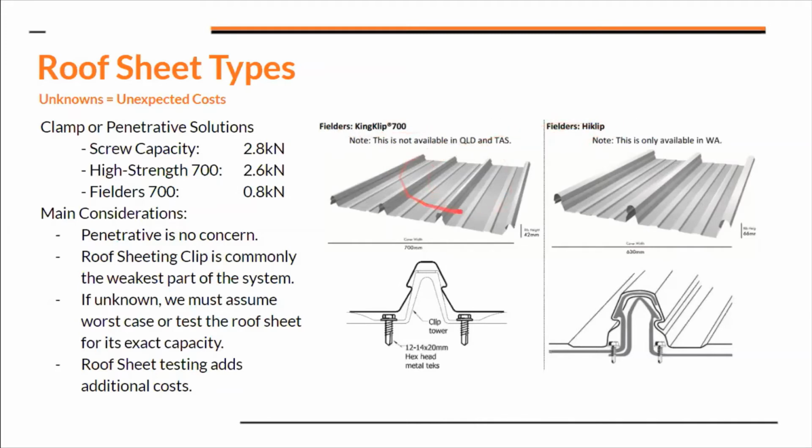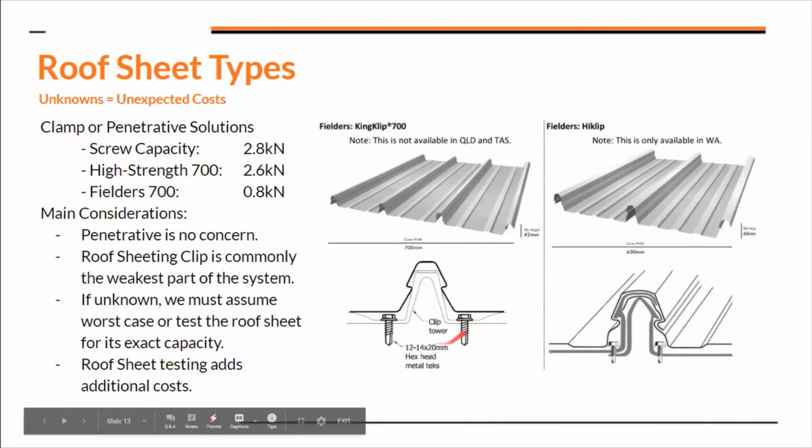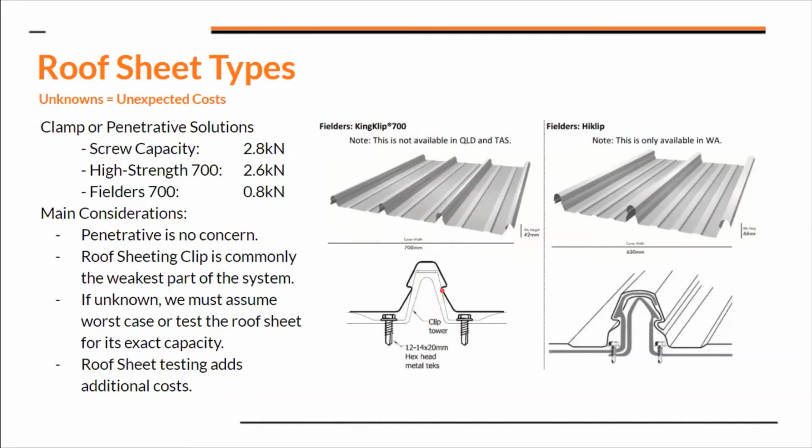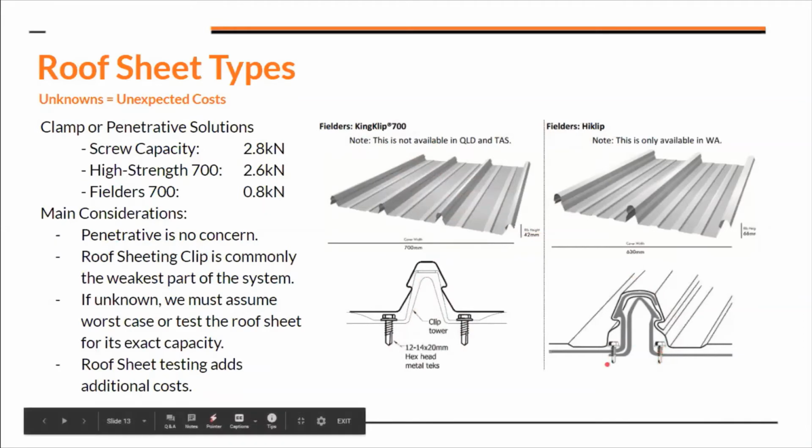Now, how these roof sheets are actually installed on site is that they have these internal clips. A roof plumber would come through and install these internal clips into the structure, whether it be timber or steel. They would screw these internal clips down, and then they get this roof sheet and pop it on top and press it down, and it kind of locks into this clip space. In the same way here, they've screwed these little things down, and then they've put this roof sheet on, interlocked.